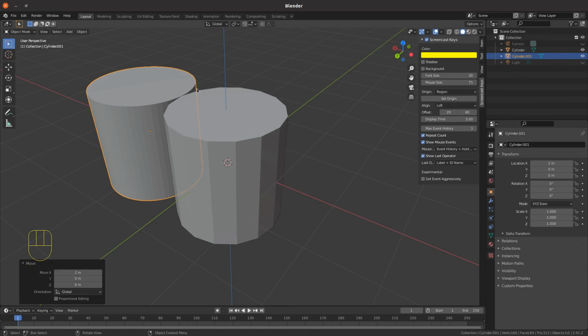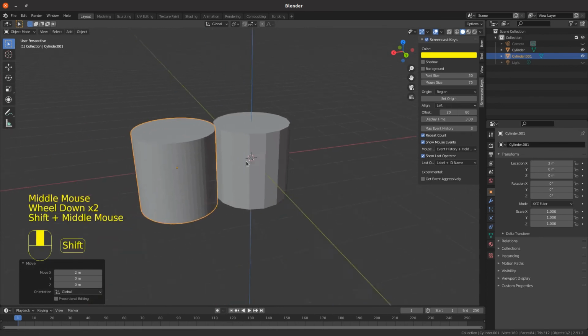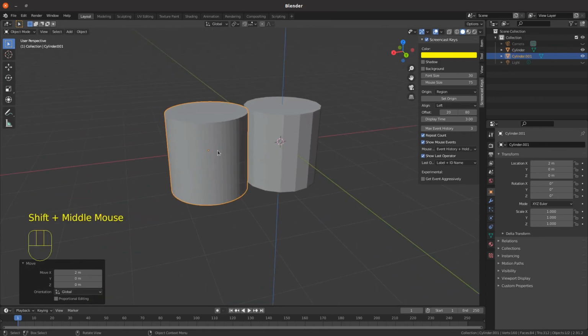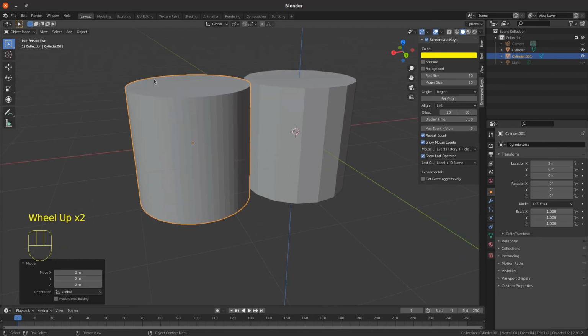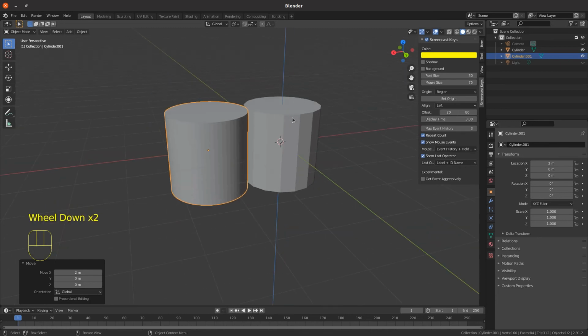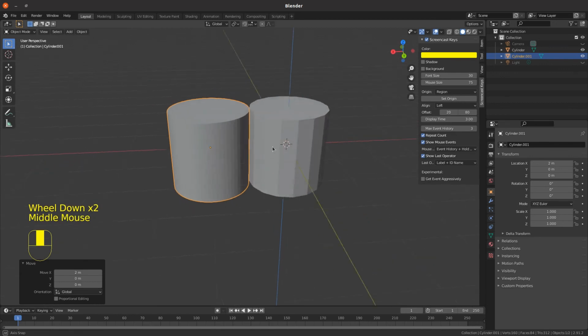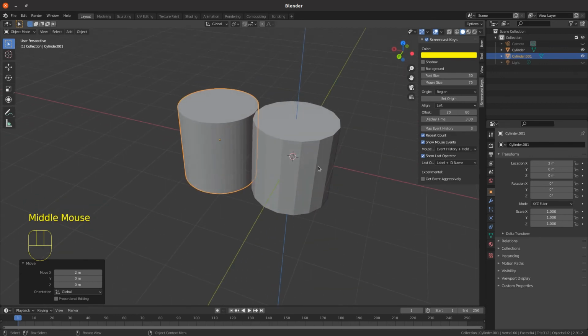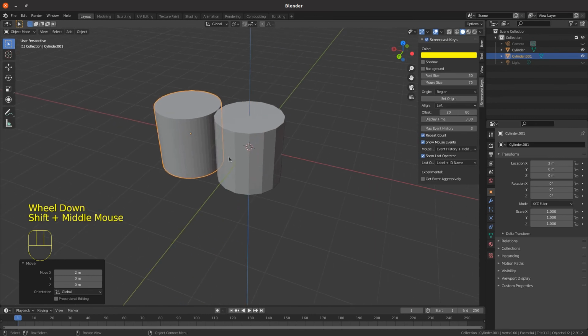They're almost invisible where you've got more vertices making up the circles. So whenever you're working on areas where you need close bends, you can shade smooth and have more vertices, so you don't see the faceting. Where things are in the distance and it doesn't really matter, you can have fewer vertices, and that faceting won't be so noticeable when it's a small item in the distance from the shot you created.